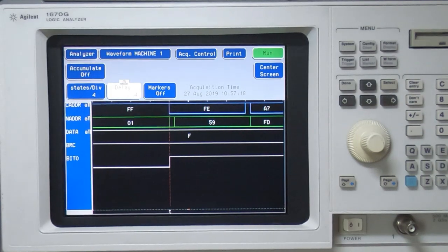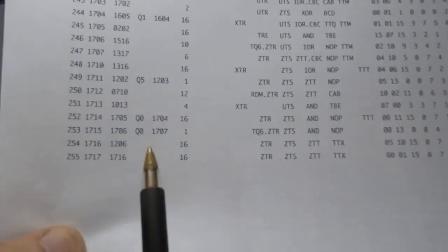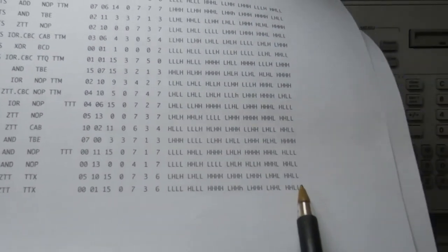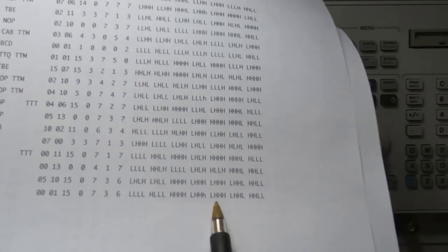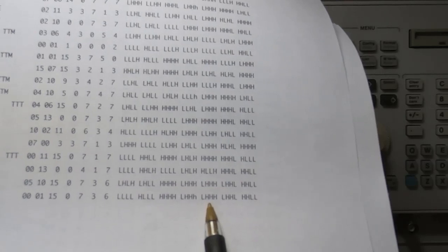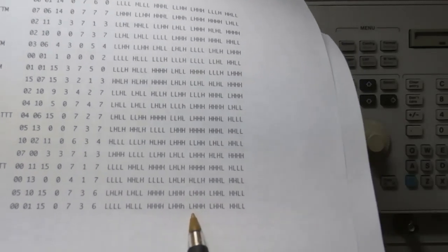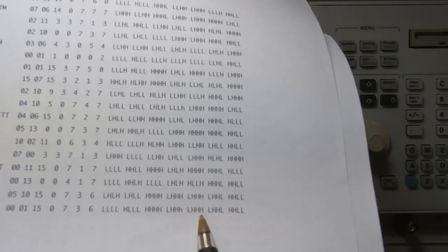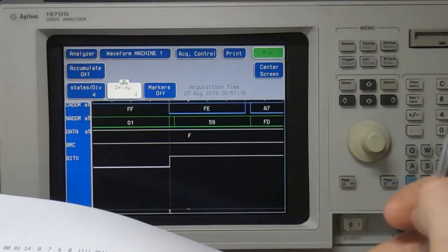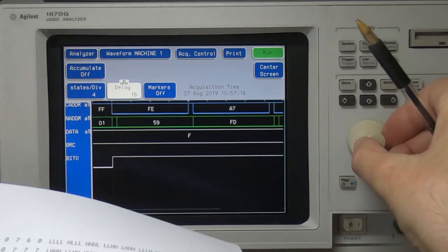So they're always high. Okay, I've obtained a copy of the disassembly listing for the microcode ROMs, and if we look at address 255, that's FF, and follow it across, then the 3rd column from the right is the data we should be getting out of the ROM we're looking at. This is ROM 7, and as you can see it should be a value of 7, and it's not, it's shown as F, and the same is true if we go all the way across.